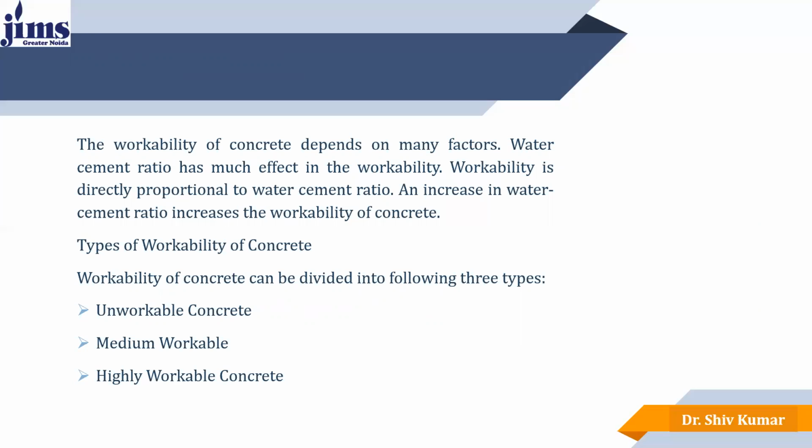The workability of concrete depends on many factors. They will be discussed later in my further slides. But the most important factor that affects the workability is the water cement ratio. The workability is directly proportional to the water cement ratio. As the water cement ratio increases, the workability of the concrete increases, and vice versa.